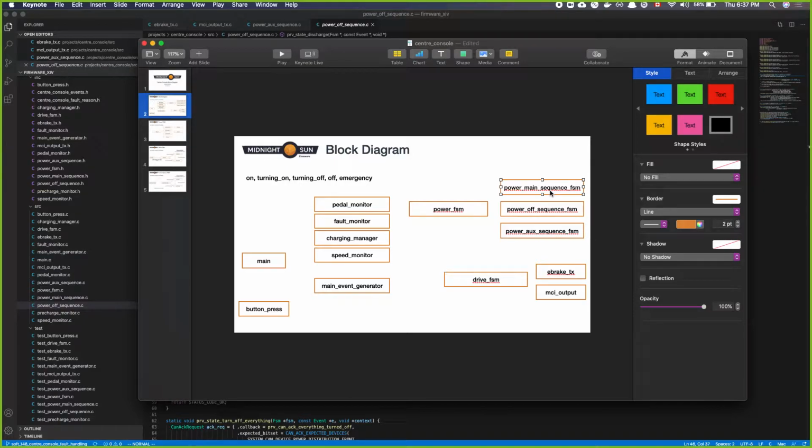Let's say you want to, for example, check the DC-DC status, and the DC-DC status is not what you want. That board can still acknowledge your message, meaning you receive an acknowledged message, but the status of that acknowledgement is going to be invalid, meaning, hey, I'm not in the state that I want to be, right? So if any of these guys fail, that's a transition fault, meaning that, let's say you wanted to turn on the car, but you couldn't.